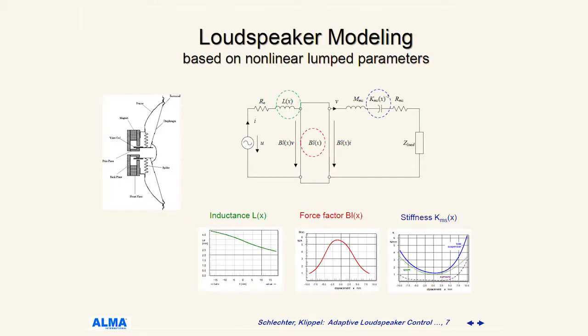Our loudspeaker modeling is based on a nonlinear lumped parameter model. You're probably familiar with some equivalent circuit of the loudspeaker. We have linear terms, and we also consider nonlinear lumped parameters like the inductance related over x and also i, and the Bl, the force factor, related over x, and stiffness over x.